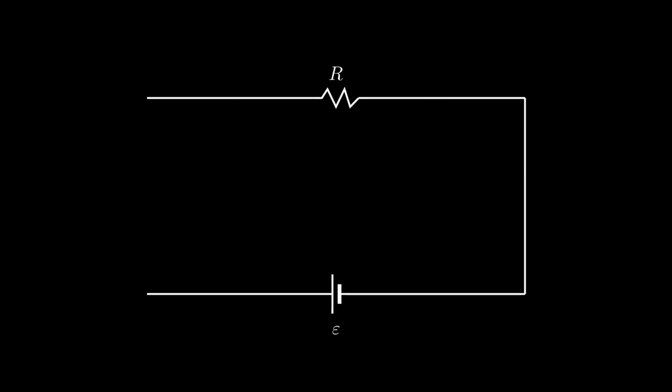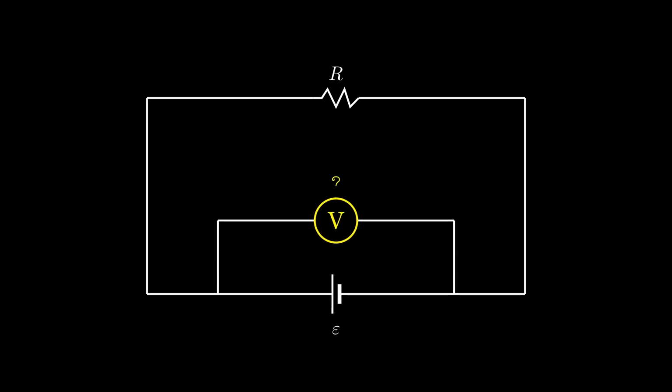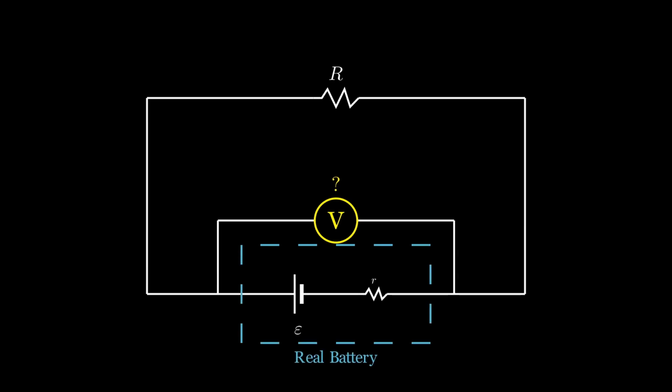If we connected a voltmeter across the ends of a battery, what would it read? This is a very interesting question, as we have previously assumed that the batteries are ideal, ergo they have zero internal resistance. In reality, however, there is, which will result in potential difference IR across the battery. Hence, the EMF decreases from epsilon to epsilon minus IR, which is what the voltmeter would read.